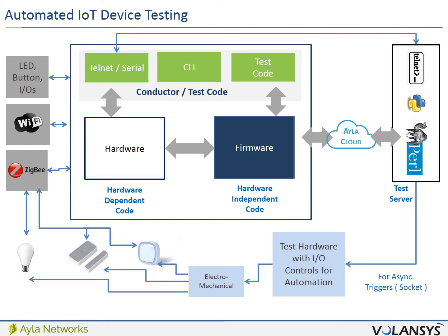Also, for doing a lot of load testing without actual hardware, such a setup can help create virtual simulated devices without actual devices being there. For example, we can create 100 virtual bulbs and do the load testing of the end-to-end system, checking how cloud, device, and mobile function when this many sensors are detected.